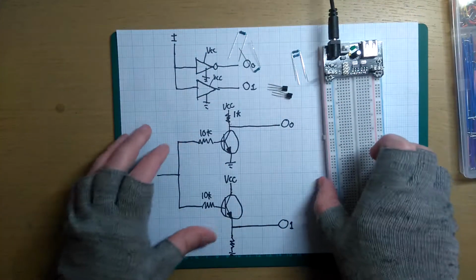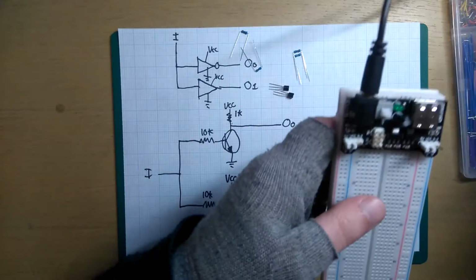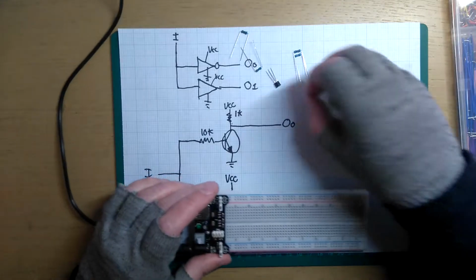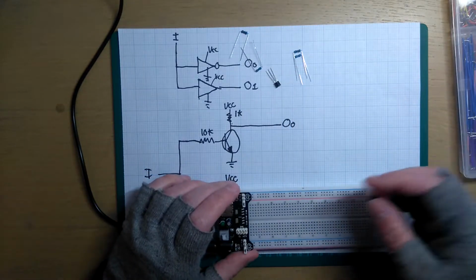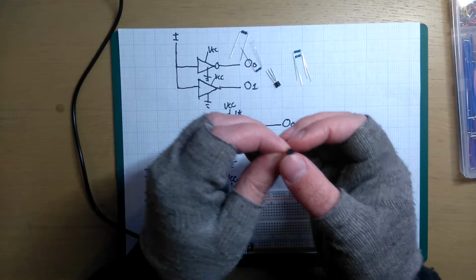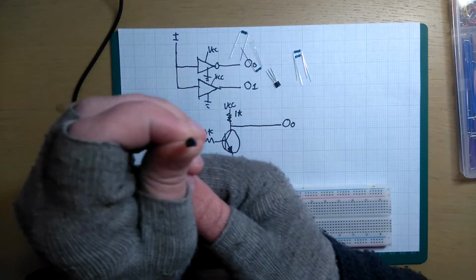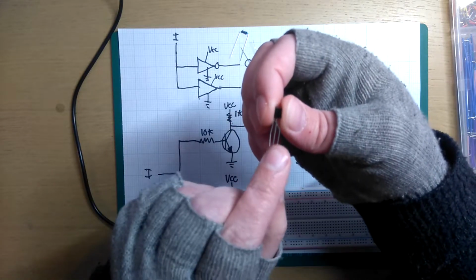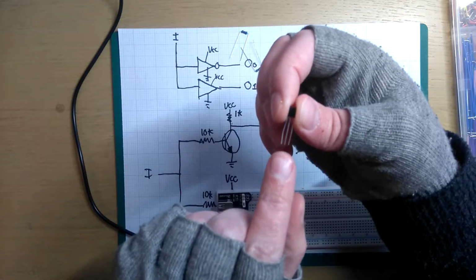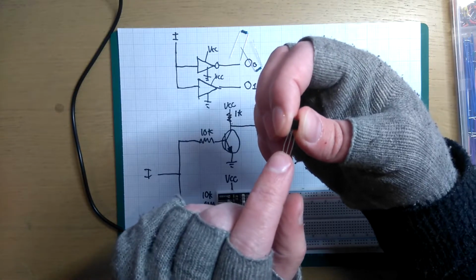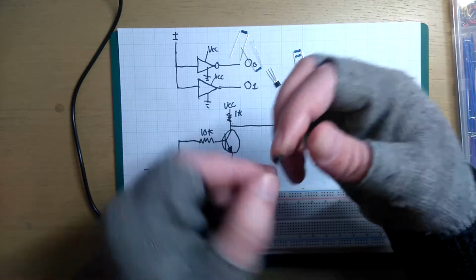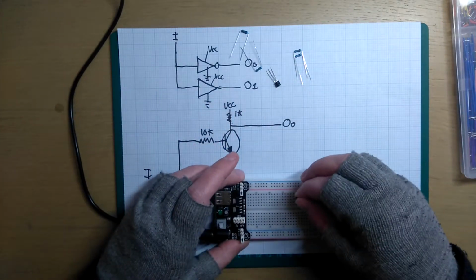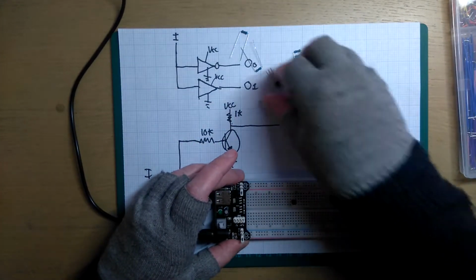Right, so let's just build these gates first. So we'll just bung them somewhere in the middle here. So you have to remember that on these, you can see the shape. There's a back here. That's actually sort of backwards. It's the collector, base, emitter. So this is the emitter, base is in the middle, and collector is on the left. But I actually want them that way around, just because I read it left to right, so it makes a little bit more sense to me. So bung these in here.